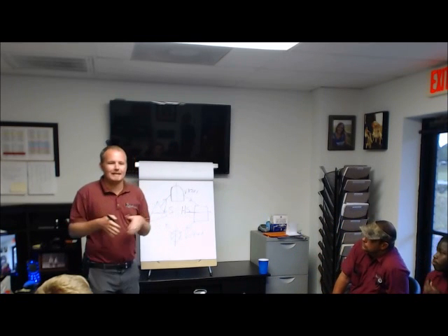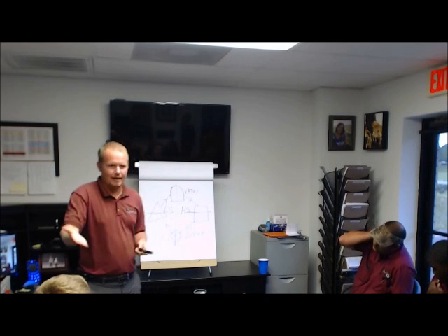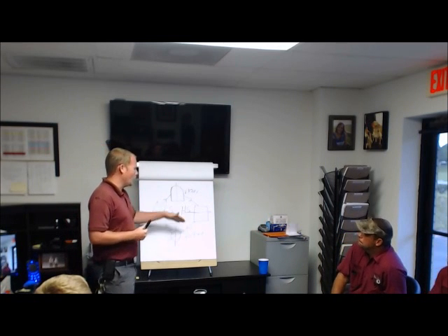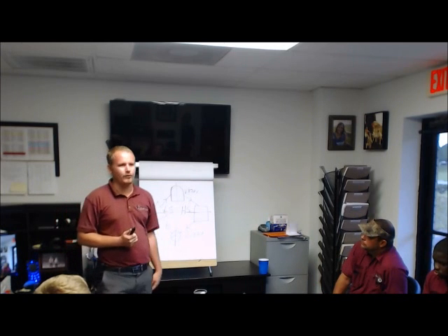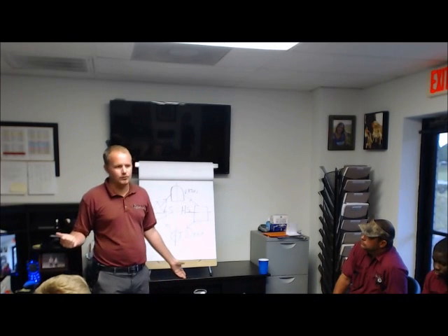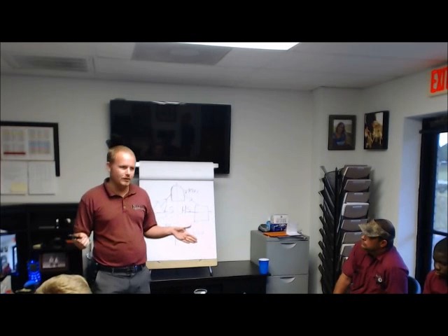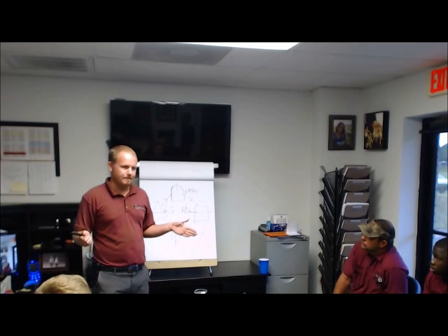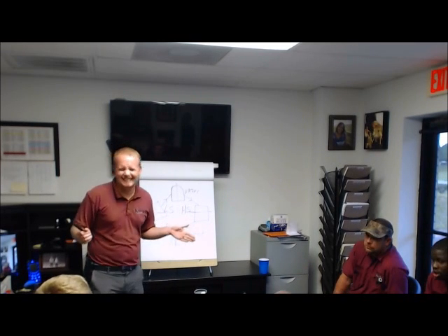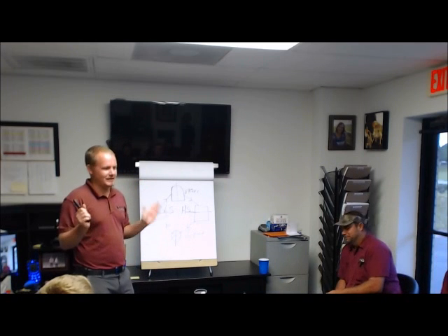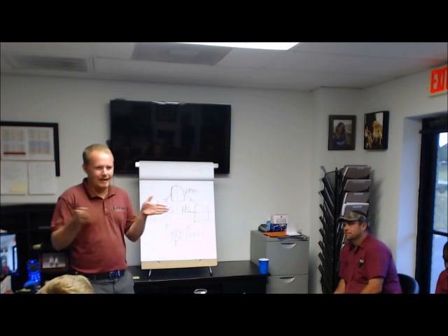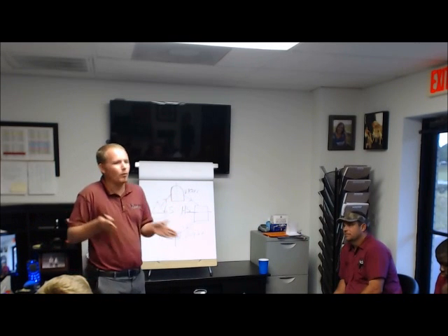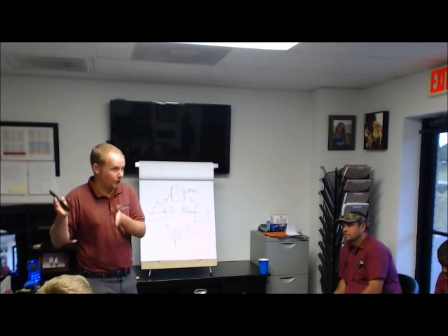What I'm saying is, though, I used to dumbly say, oh well, yeah, 1 degree of subcool is actually ideal, but you have to add more because you don't know how accurate your equipment is. Actually, that's not true. You know what the perfect amount of refrigerant to have in a system is? What the data plate says. Yeah. The exact amount that it's supposed to have in it. Meaning the exact amount it was designed for. Because if you add more than what it was designed for, then you're going to cause other problems.